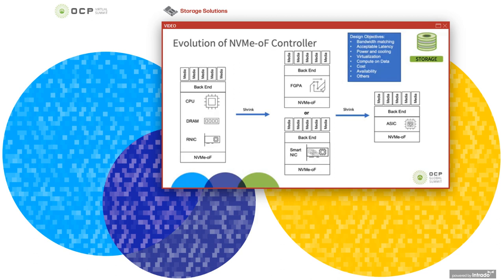As is common in technology, we went through a shrink process and two tracks sort of emerged. The first one is one where we have smart NICs or SNICs. Those smart NICs really represent microservers that run on small form factors that look like NICs. Instead of server class x86 CPUs, most of these smart NICs have embedded ARM cores. The second track has FPGAs replacing those embedded ARM cores.